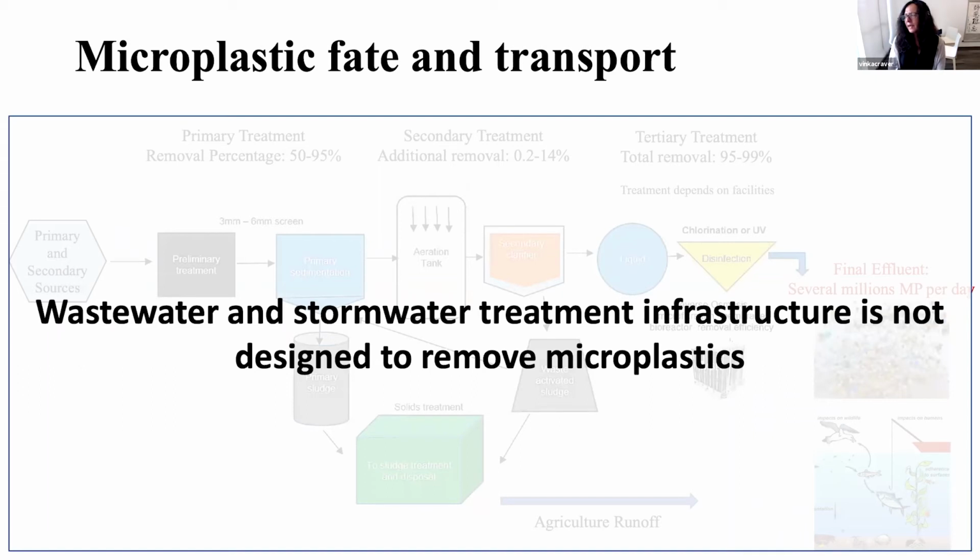And why? There are different mechanisms, but we rely heavily on sedimentation, and the particles are large enough that they are going to be settling and we will be able to remove and separate them. Now, if we're thinking about microplastics, they are very small. And also the density of the microplastic is very similar to the density of water. The proof is that when you have some plastic, it usually floats. There are not that many plastics that are much heavier than water. So they tend to float.